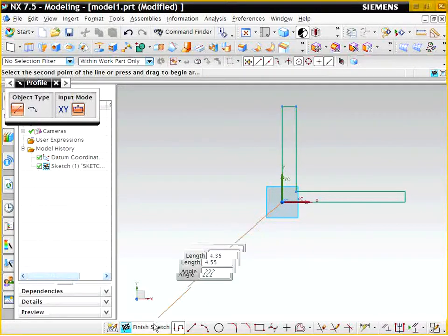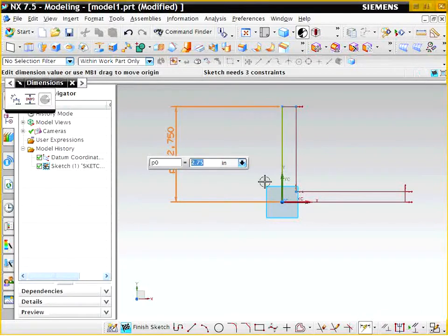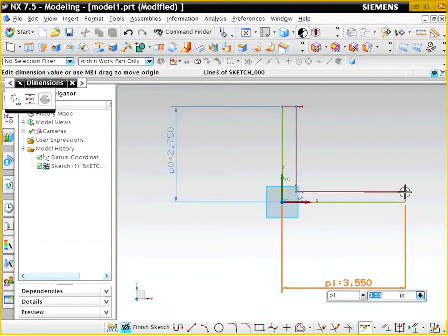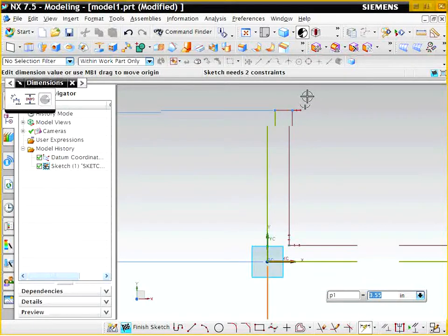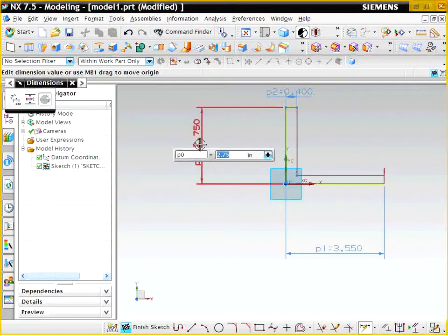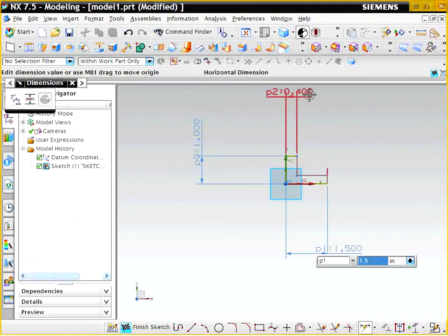And we'll go ahead and set some of these constraints here so that we know exactly what these lengths are. So this length is there, this length is here. Let's see, I think that I need this length as well. So let's make sure we select this length, okay? And now let's put in some of the values that are in the text. This is a value of 1. This has a value of 1.5. And this has a thickness of 0.1.